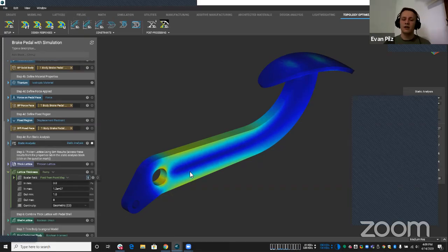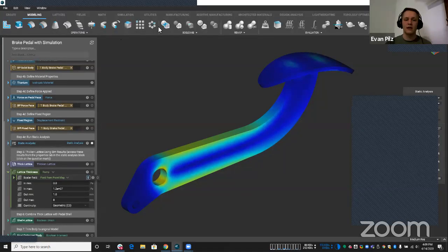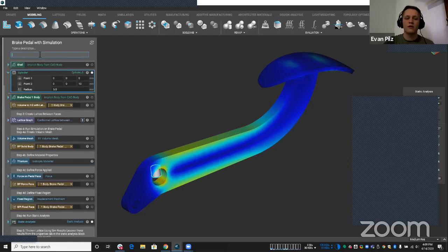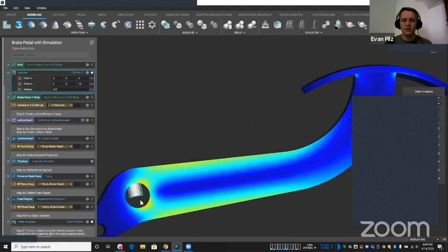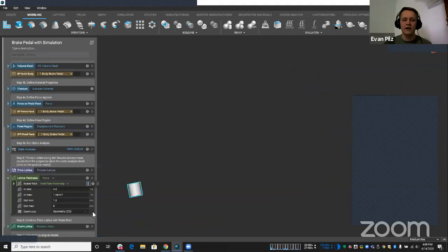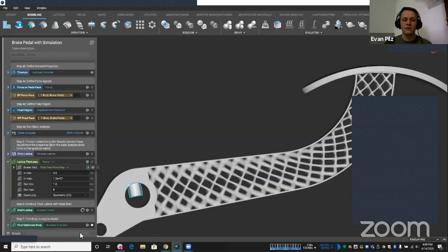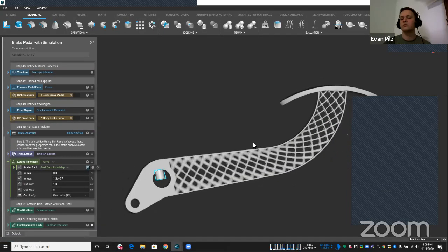But if you see that, you can come in and add in your thickness, like I showed you with that threshold slider, or you can actually add in something like a cylinder somewhere if you need to. If you want to add an extra beam for support and thickness, this is in implicit format, so it is our final option here. You'd be able to come in here and add in this cylinder for added support at any point that you need it. So if you have a beam that's a little bit too thin and you want to thicken it, there's a couple different ways you can go about that.